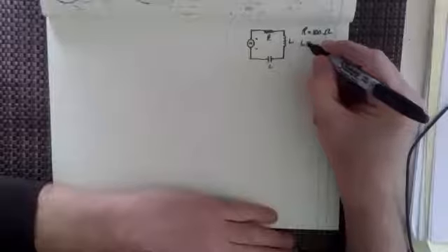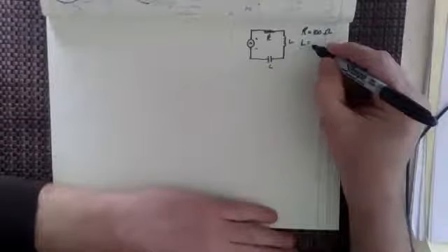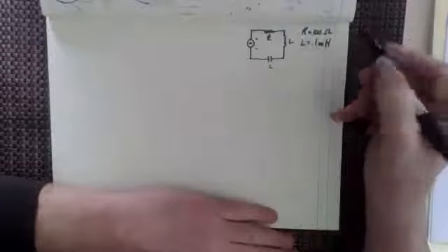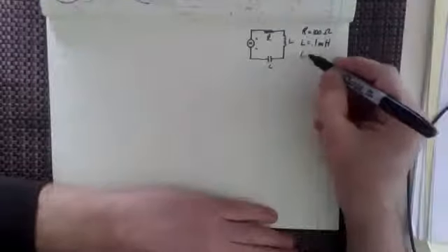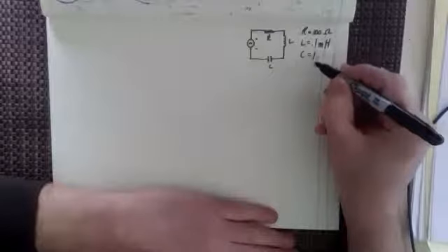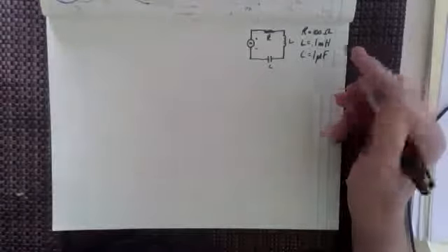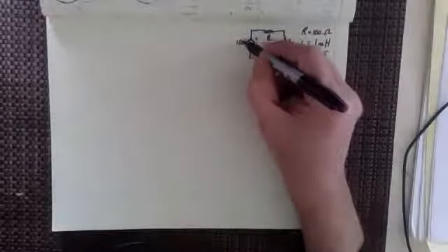For the inductor, I'm going to say that that is a 0.1 millihenry inductor. And then for the capacitor, I'm going to go with a 1 microfarad capacitor. So we've got all three of these, and then we can just say that this is a 10-volt peak power supply that's coming in there.